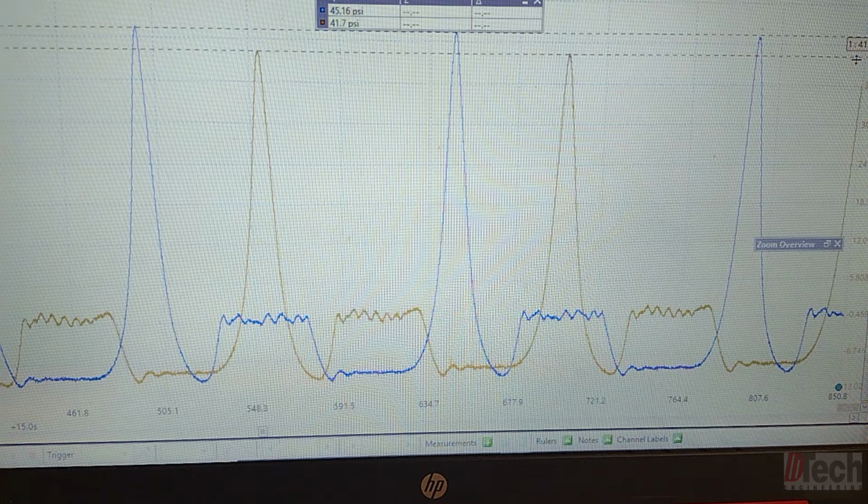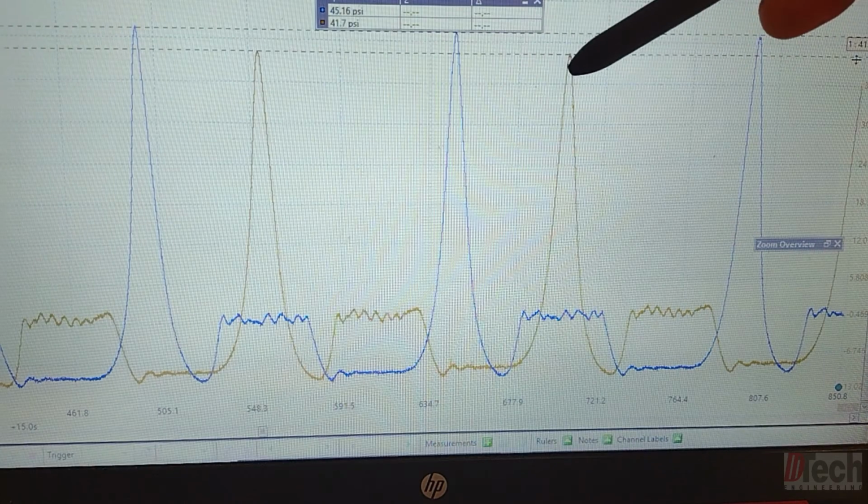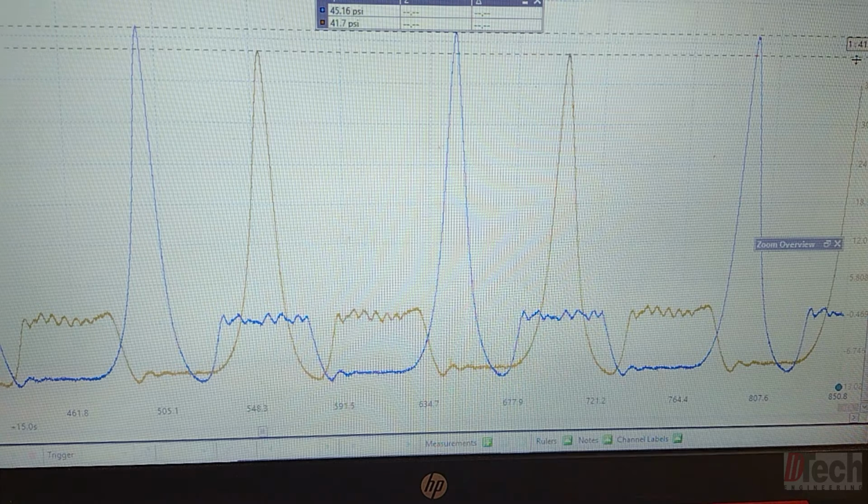Now, if you were to have gone directly straight into in-cylinder running compression pressure and done this test on cylinder number 8, the capture from compression doesn't look like too much of a faulted waveform. The towers don't even appear to lean as bad, because again, we're only losing about 4 psi here at idle during running, and there might be some sort of a lean, but not enough that you